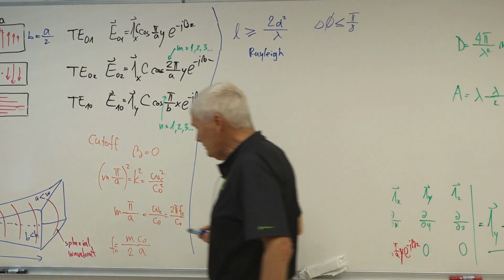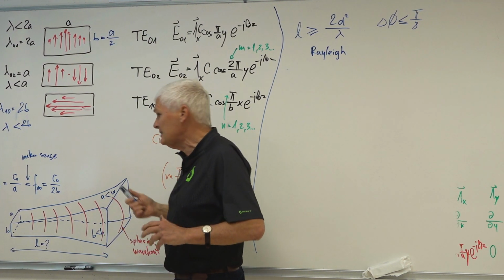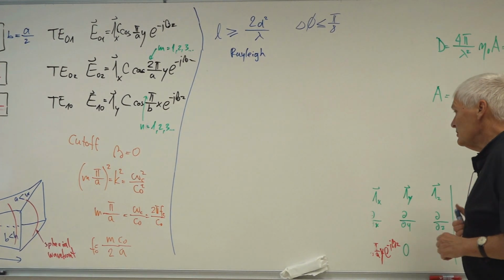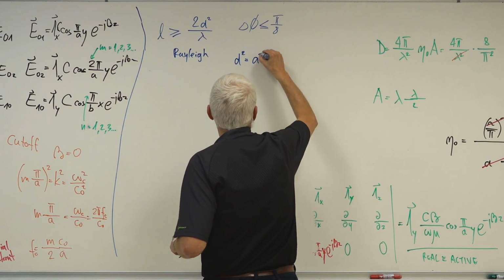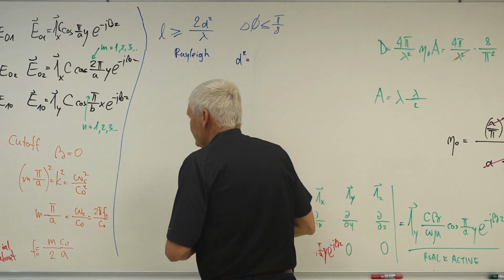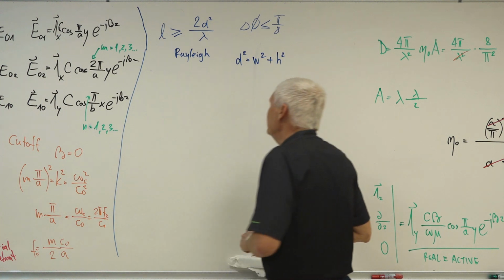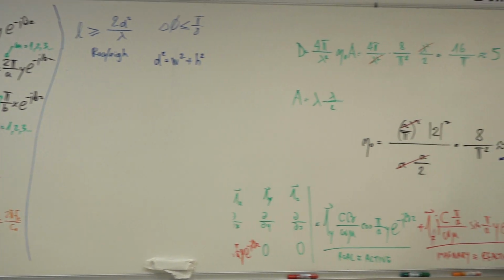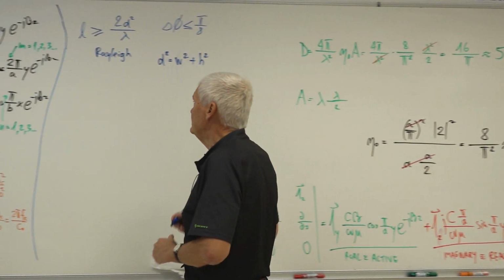It's exactly the same thing as the far field of an antenna, but here we are moving actually inside an antenna, but it's exactly the same problem. Exactly the same thing we are talking about. So let's see, and this d squared, what is d squared now? According to Pythagoras, d squared is a squared plus b squared. Sorry, not the original waveguide, but the aperture, so width squared plus height squared. Okay? We know what we are talking about. What are now the conditions, say, for this thing? Let's try a simple example.